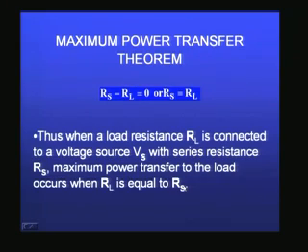Later on you would find, when I build an amplifier and connect it to a loudspeaker, usually loudspeakers are coils with magnets and a diaphragm and all that, you all know that. So it is a simple copper coil, and the resistance of the copper coil will be very, very small. An amplifier is something which will magnify an input voltage at the output to a large value, and during that process, when I look from the outside of the amplifier, the amplifier can be imagined to be a voltage source with a resistance, the internal resistance that we already talked about, and that resistance can in general be a very large value.